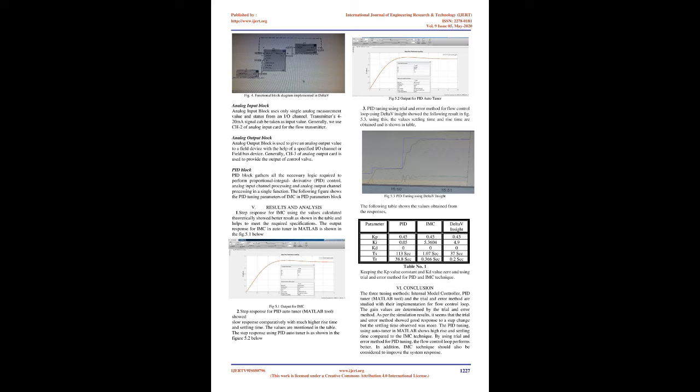For system identification. PID is one of the powerful but complex controller modes, combining proportional, integral, and derivative control modes. It has following advantages. A. One-to-one correspondence between P and EP. B. Eliminates offset of P mode. C. Provides fast response. Mathematically, PID controller is written as P equals Kp.EP plus Kp.Ki.∫EP plus KpKd.dEP/dt plus P(0), where Kp equals proportional gain, Ki equals integral gain, Kd equals derivative gain.